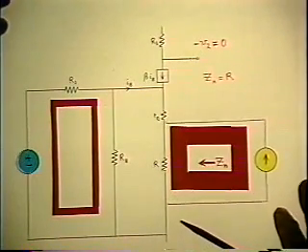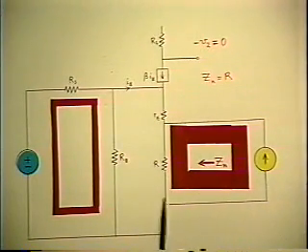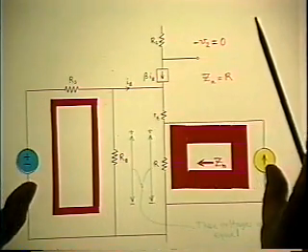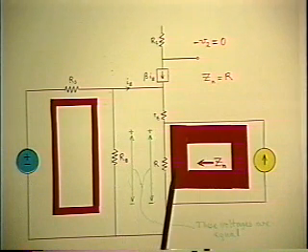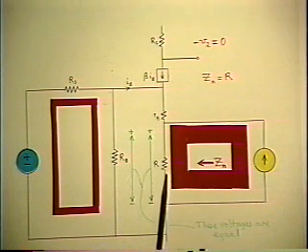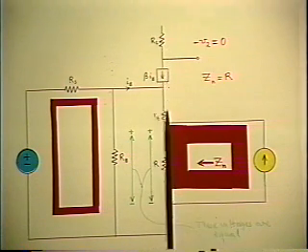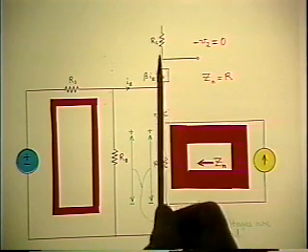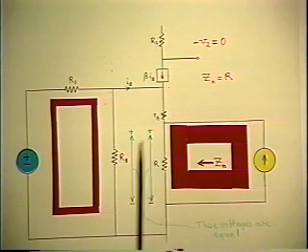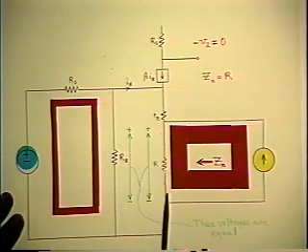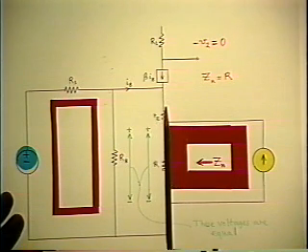even to the final stage, which is eliminating the null from the picture and showing only the remaining two loop currents. In other words, we set up the condition that the voltage drops across RB and R are equal. And this illustrates perhaps even more clearly why it's only the null that you need. Because implicitly, to get a null, the voltage across RB must have the same value as the voltage across R, because that's how you get the null.